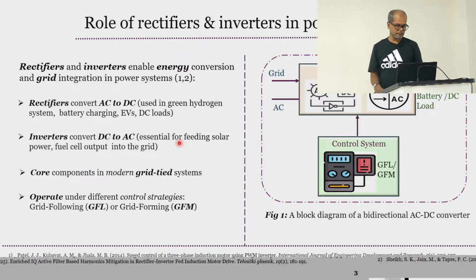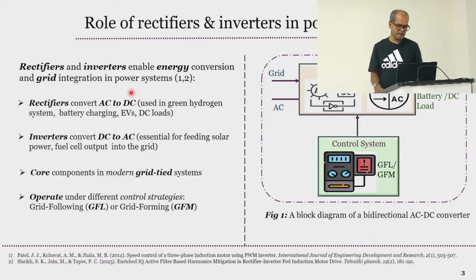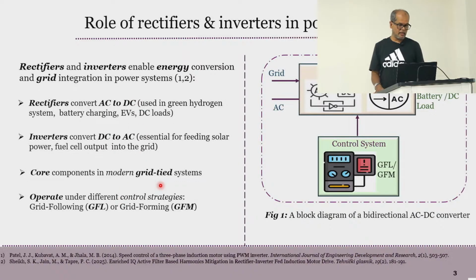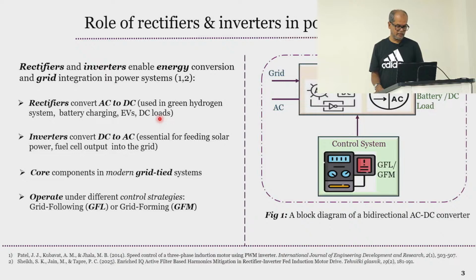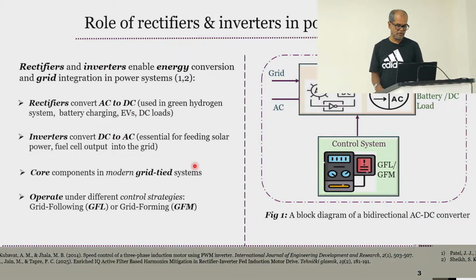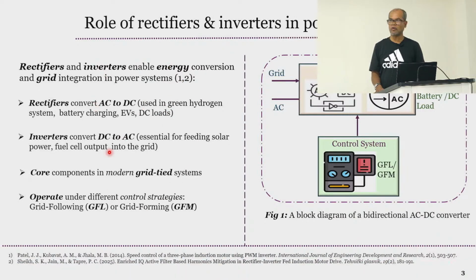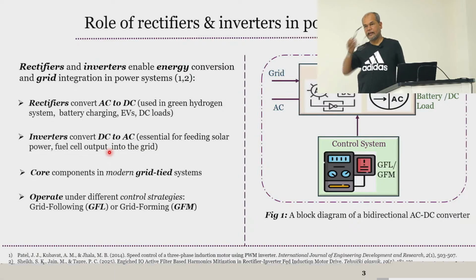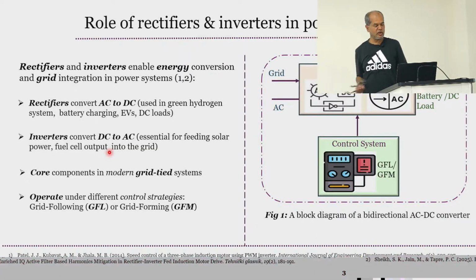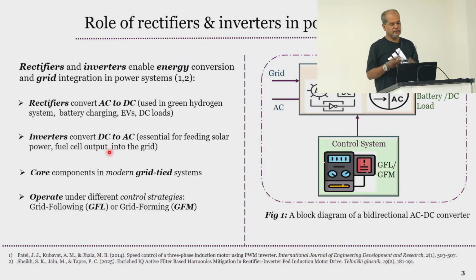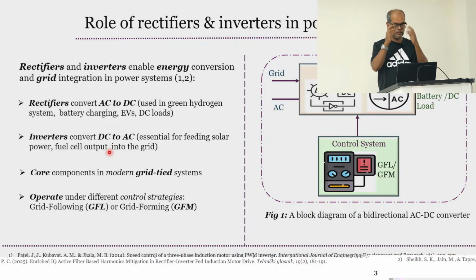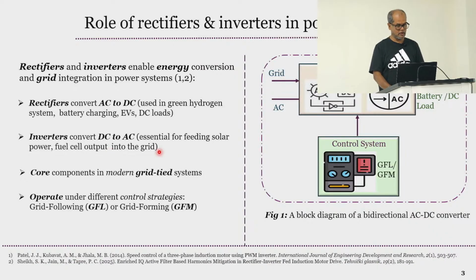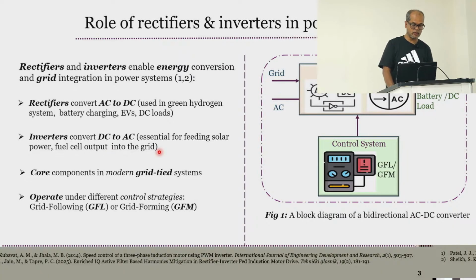because, as I said, there are so many power electronics devices in use. At some stage, it's not that power electronics is actually dominating the grid dynamics, but when you have 70-80%, they actually dominate the dynamics. At that time, definitely we need to do the electromagnetic simulation, not electromechanical.